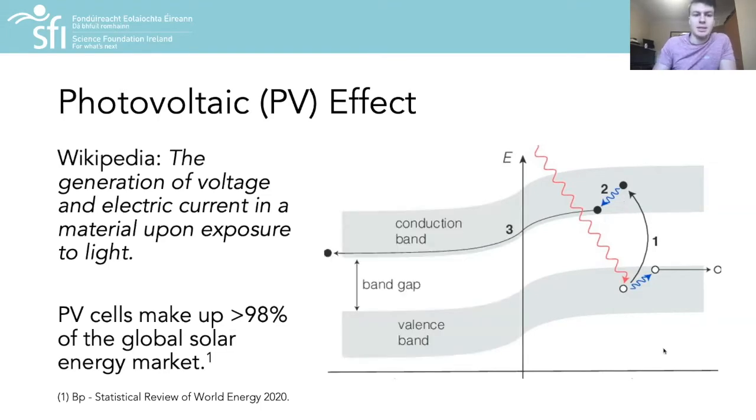The next step in a solar cell is to use this excited mobile charge carrier to generate electric current. To do this, they must be separated. We must separate the excited electron and the positive hole that it left behind. This is typically achieved using the PN junction you saw two slides previous. This is the concept upon which the vast majority of solar cell devices are based.